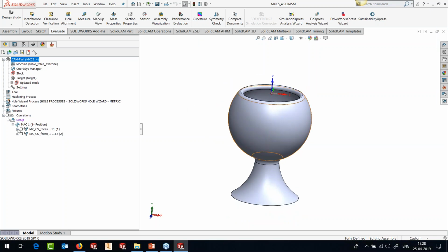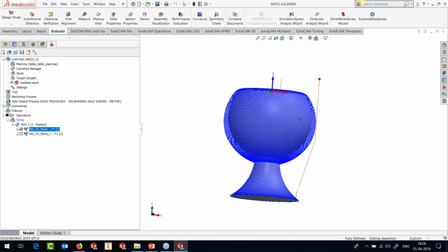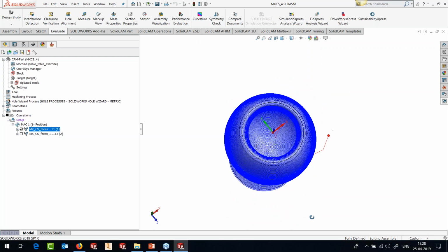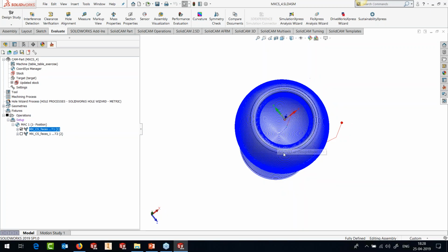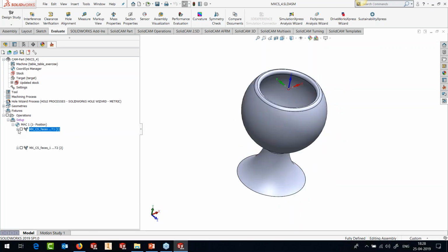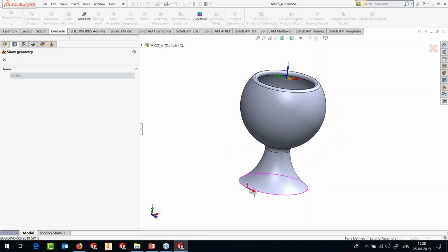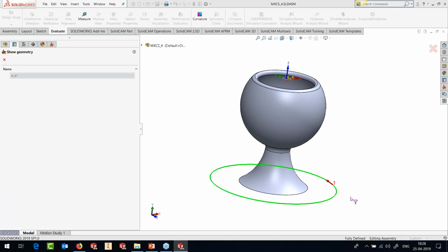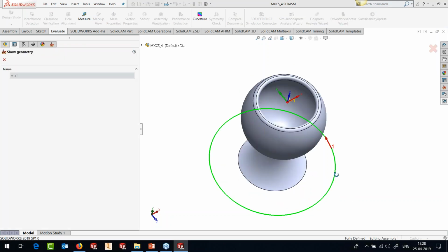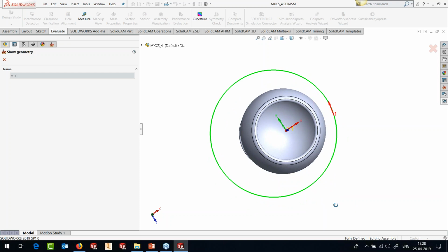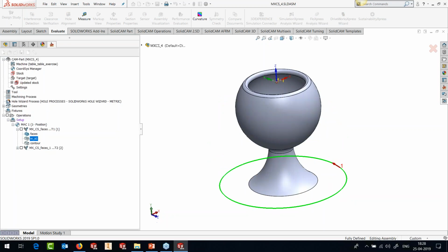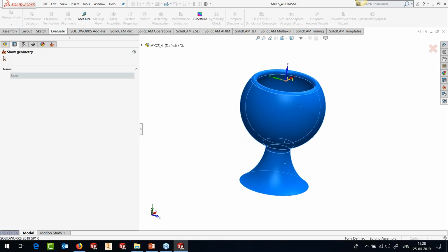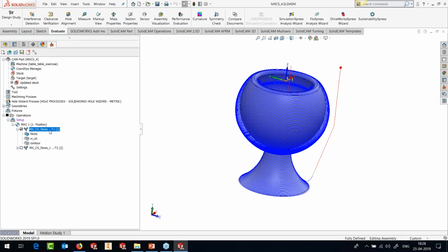Now, with the new function, I can immediately generate a single toolpath right from the start till the end. If you look at the parameters defined, I have asked SolidCAM to generate cuts parallel to this curve, with this particular curve as my boundary. It's a big part, that's why it's the boundary. And I've selected all these faces, and this is the toolpath I generate.